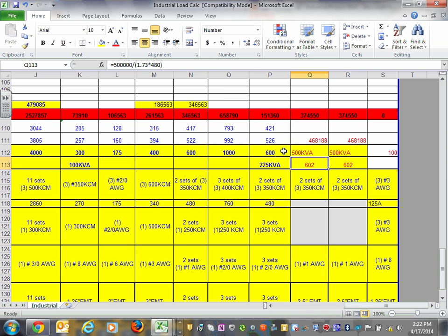So the amps that you see at the bottom here are my amps on the primary side for the UPSs, and also on the primary side for the PDU. I took the value that I sized and divided by the voltage and came up with these 2 amps. In order to size my conductors on the primary side of the UPS and on the primary side of the PDU, I want to remind you guys, inside all these numbers is 1.25, already multiplied for the continuous load.